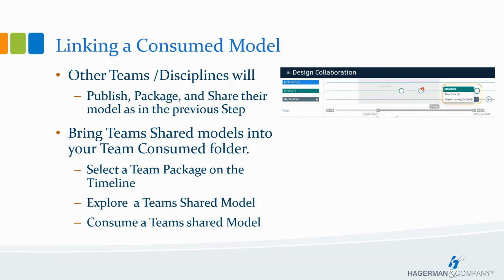Once another team has followed the previous steps to create a package, your team can explore the newly shared packages in BIM 360 collaboration module by selecting the open circle in the timeline. So here, if I am the mechanical and I want to consume the structural team's latest package, I can select on the open circle so that I can view the structural latest package.